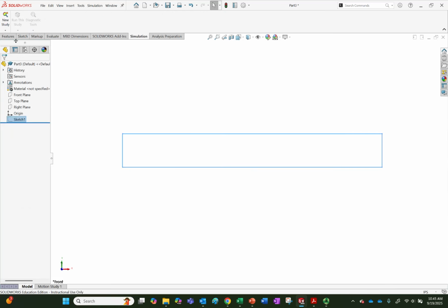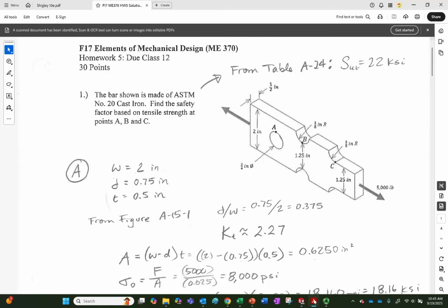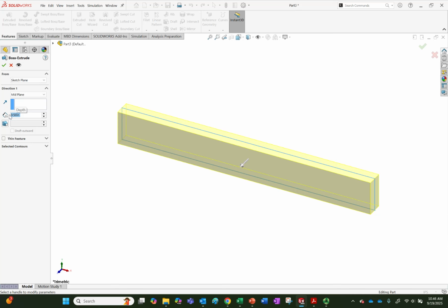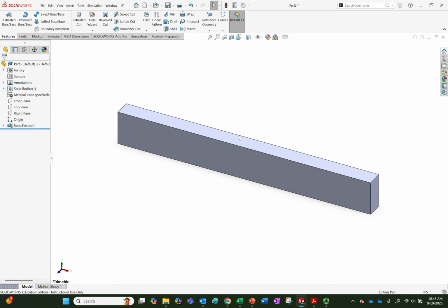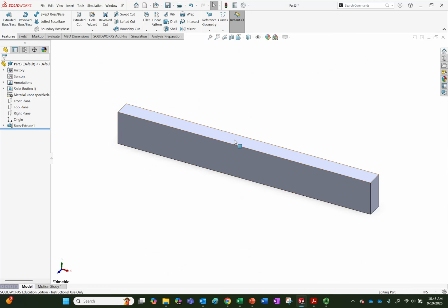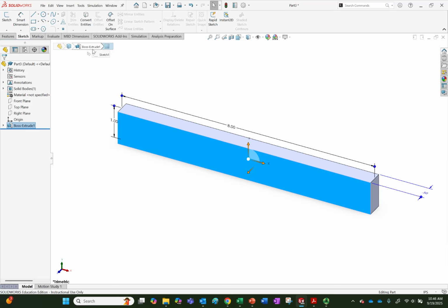We'll make it this way right here, and then I'll extrude it. I don't have to go halfway down the plane, but I am going to. So I'm going to make it 1/2 inch wide, but I'm going to go mid plane for it. Anyway, boom. Now I'm going to put the notch fairly close to the middle, maybe a little off to the side, because I don't want it to interfere with this over here. So I'll make that a sketch on this face.